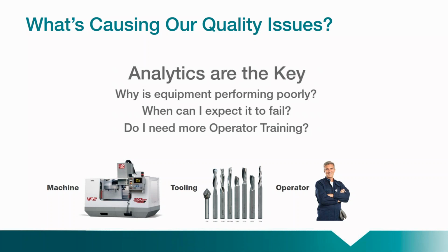Incorporating preventive maintenance can tell you things like when you should be changing your tooling, or if you should adjust the speed of the feed for the bar stock, before it affects any of your production, instead of waiting to produce scrap and creating some waste. Which is great, because anyone who's ever managed the factory floor can tell you that maintenance schedules affect production schedules, right? So you'll become a lot more efficient.